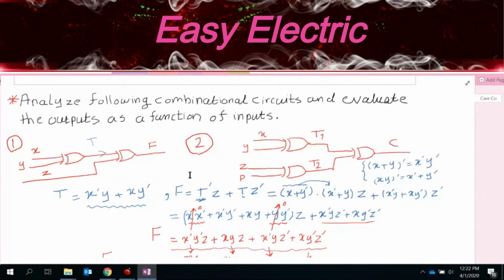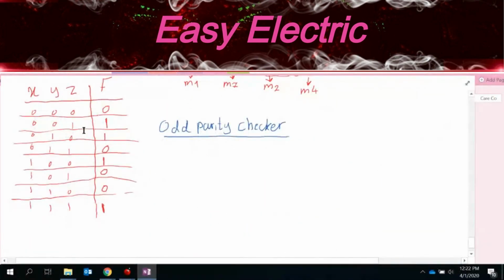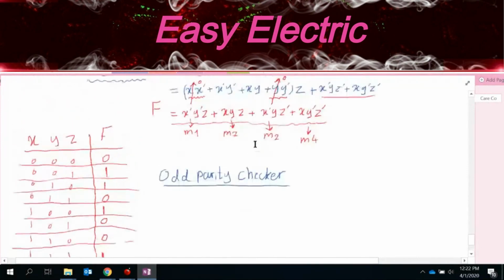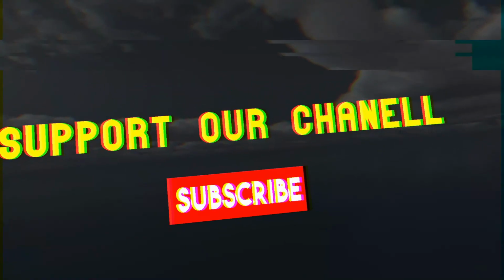But whenever you analyze, you already have the circuit, but here you want to understand what the main or basic function of that circuit is, which means you need to find the outputs based on the inputs that you have, draw the truth table, take a look at the truth table, and with the truth table you could find one basic function inside that.